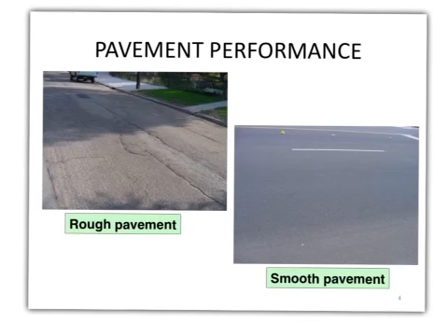So here is an example of two different pavement performances from the functional perspective. We have a very rough road here. As you can see, there are lots of cracks. Besides cracks, the texture of the surface is really rough, and typically this is an indication that the road is rough and we need to think of something to improve its smoothness to reach what we see in the other picture here.